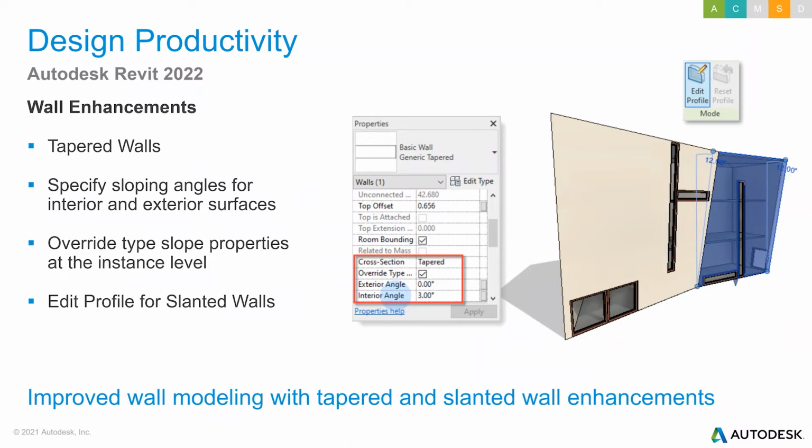If you are familiar with the variable thickness floor objects that have been in Revit for quite some time now, where inside the type properties, we would turn on the variable part of a floor, the walls are actually much the same now, where we can have a variable part of the wall that we then use for the tapering and sloping. So a much welcomed improvement after years of using masses to generate these sloped and tapered objects.